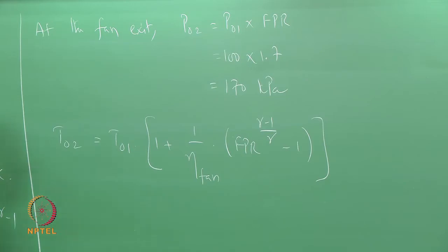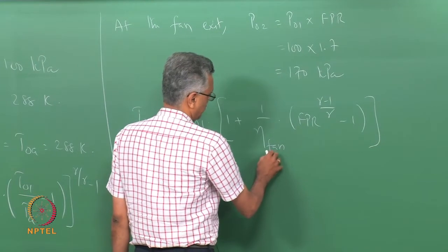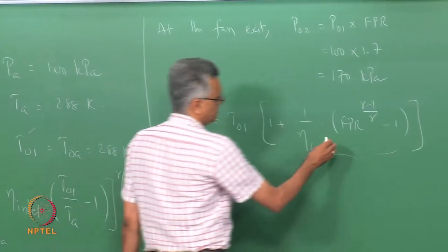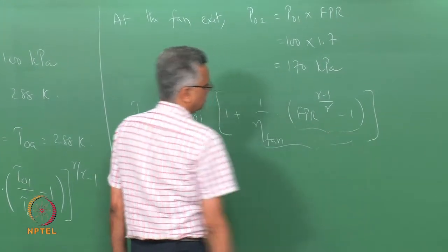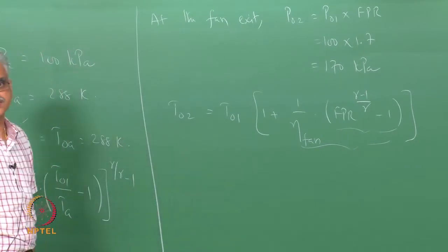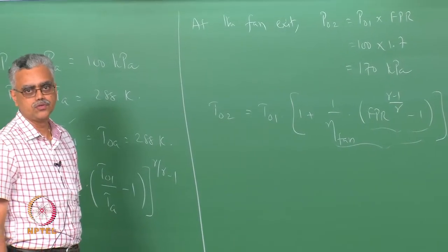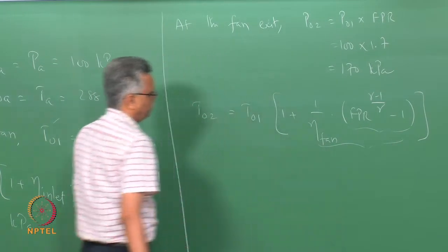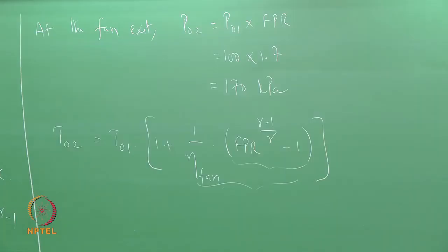You may recall that this quantity inside is nothing but T02S, and then we use the isentropic efficiency of the fan to calculate T02.